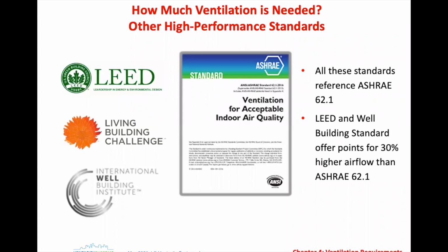And then there are some variations. Some of these standards are going to have a variation that is a little bit different than the regular code. So LEED, for example, and the WELL Building Standard will both give you extra points for a 30% higher airflow rate than what ASHRAE 62.1 requires. So by doing more ventilation, they're giving you extra points.